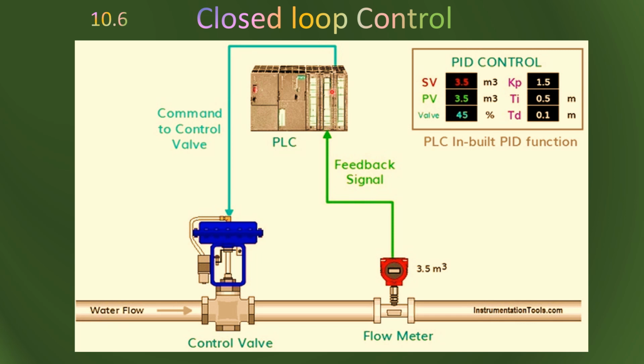inside the PLC. Some of the PLCs have modules for the PID controllers, adaptive controller loops, lead lag controllers. Those modules are available and you can use them directly. The PLC we are using here in the classroom for the lab is the Micrologix 1400. It has a built-in PID controller. Of course, you can write your own PID controller in the software using the arithmetic instructions, but doing that is a slow process. So we need a little bit higher processing ability of the processor to implement the PID controller computations.